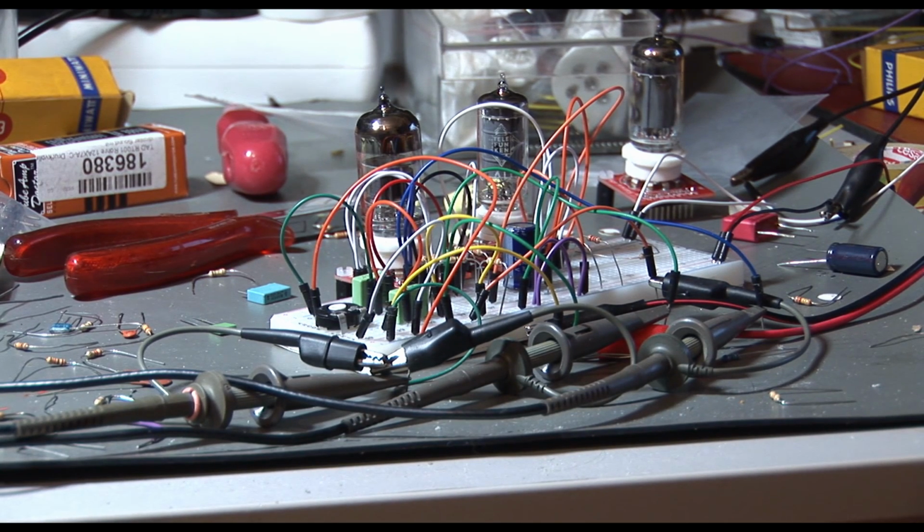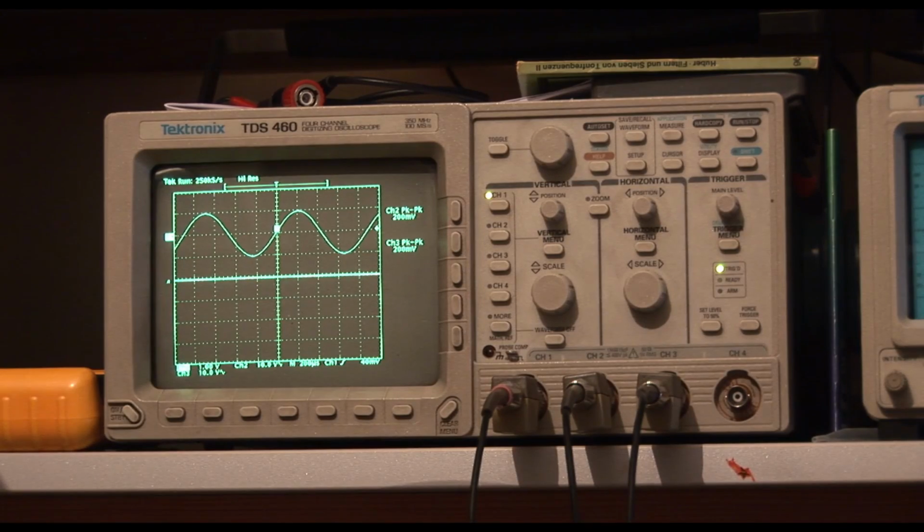Now let's move to the oscilloscope and repeat the measurements which we did before, but now with this current sink. First of all, we will test it in the differential mode. So I will connect the second input to ground, and the first input to the signal as we had it in our first test, in our first video. Now it's hooked up that way. First input is to signal and second input is connected to ground. And now let's turn on the circuit.